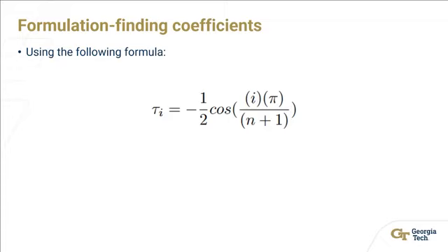So how do we create a perfect pulse? This formula shows how to generate the coefficients of a perfect pulse. A perfect pulse will have n plus 2 coefficients, so a p4 perfect pulse will have 6 coefficients. The coefficients belonging to a Pn perfect pulse describe the locations of the n transitions of the Pn pulse.